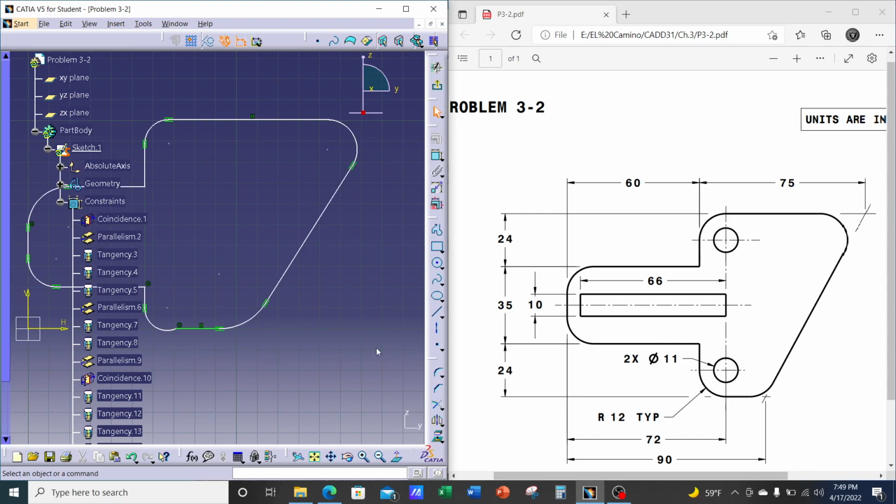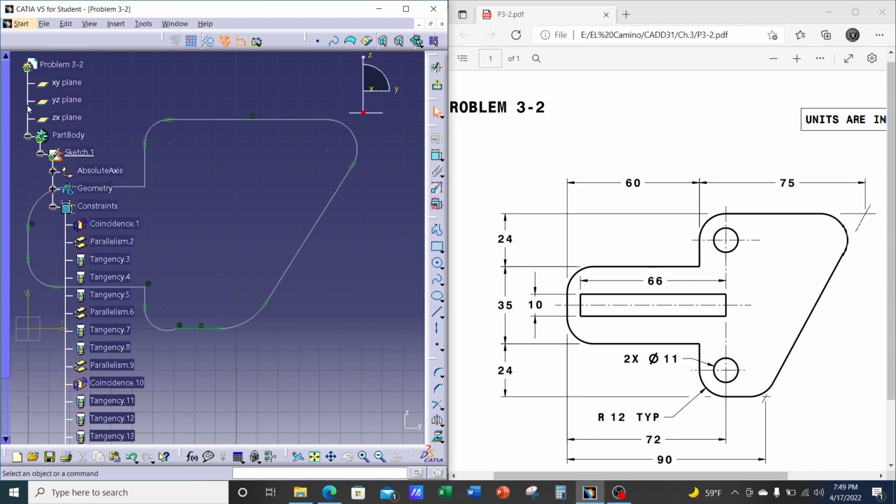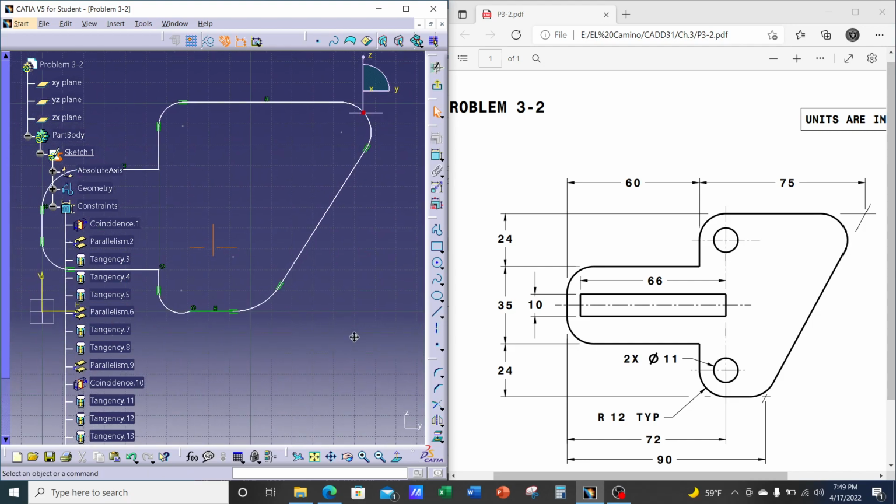If you click on it, it'll exit that CATIA tree mode. All right, so we're out of it. If we click back on this white axis, we're back in tree mode. Or you can always click on the white branch to exit, and now we're back in model mode.